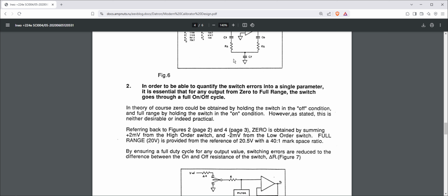The world's most linear production multimeter has declared the Woodward Synchronous PWM DAC linear down to plus or minus 0.1 ppm. But once again, an ugly artifact rears its head. There is a 0.3 ppm spike at 0. Zooming into 0 by successively decreasing the range and increasing the resolution of the INL runs by 10, it is clear that the issue is localized around 0 and leaves a smear over 10 millivolts.